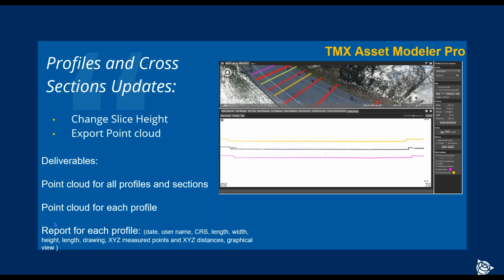The point cloud will be exported for each section, but also for all of them. So multiple files will be created, and for each profile a report will be generated. The report is very important for people who are looking into specific things. The report contains the date of creation, the username, the coordinate system, length, width, and height dimensions of your profile or section. It also provides a drawing, a schematic view of your section.